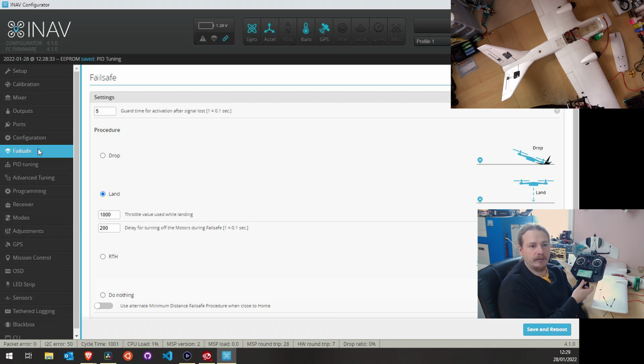I've used both in the past with no problems at all. But yeah, hold or no pulses. They both send the failsafe bit to the flight controller, so the flight controller will basically do the work for you. If you're using Crossfire, it needs to be set to cut as the failsafe mode. And again, that will send the failsafe bit to the flight controller and it will take over.